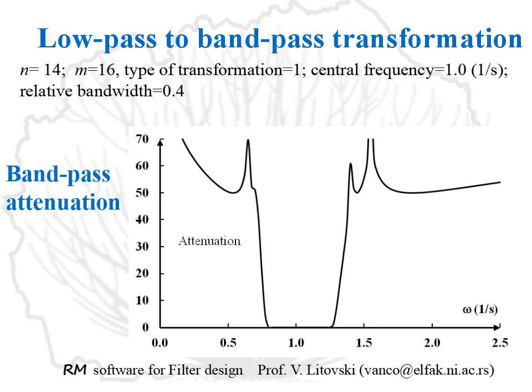Here is the attenuation characteristic of the bandpass filter. One can easily recognize that there is no arithmetic symmetry when looking at the passband, and that the symmetry is geometrical. This example was purposely chosen with a broad passband, relative bandwidth 0.4.